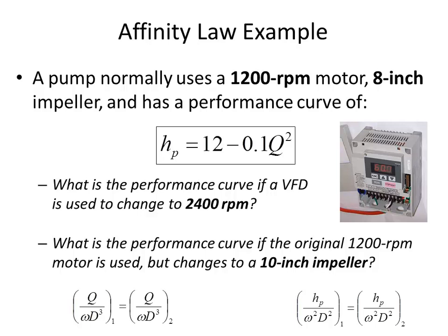So think about it in terms of benefit. What's the benefit to going from an 8-inch impeller to a 12-inch impeller? Well, you can get a whole variety of flow rates through either pump, but it's related to flow. You're losing less per flow. Precisely. So if you look at this 0.1 in the original pump curve,